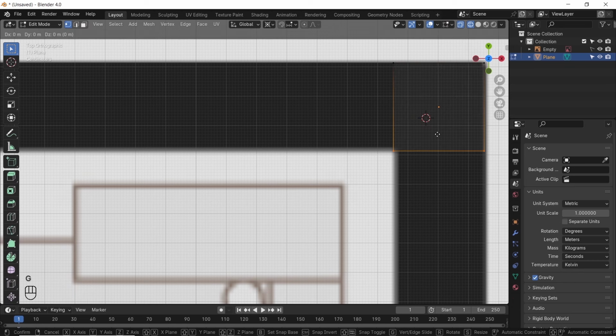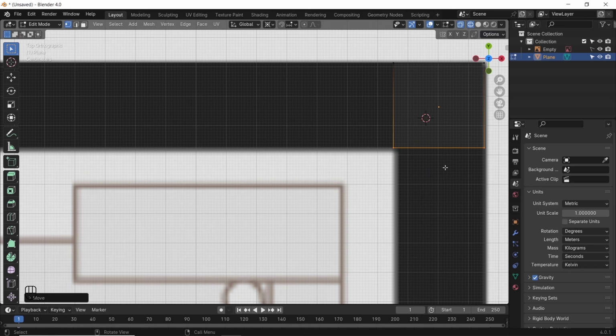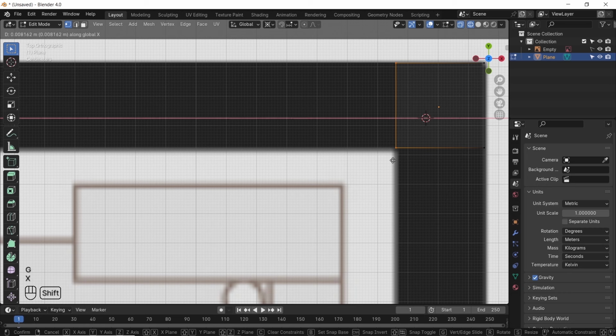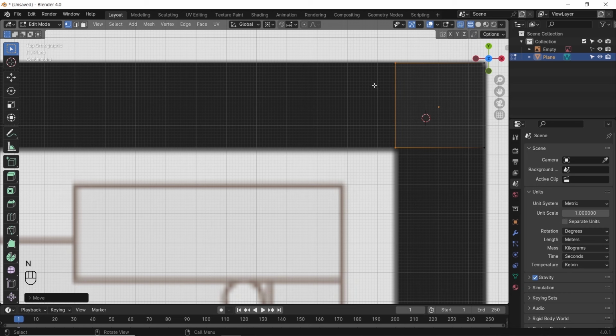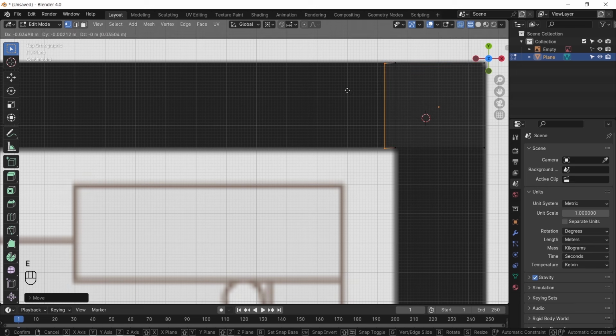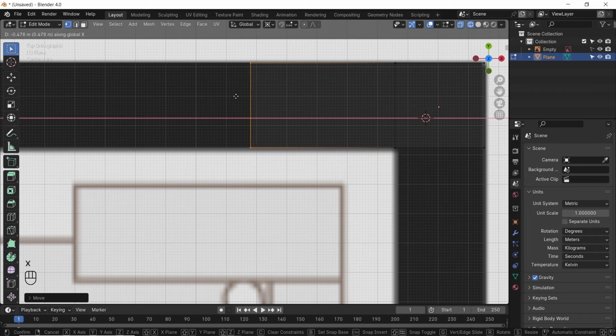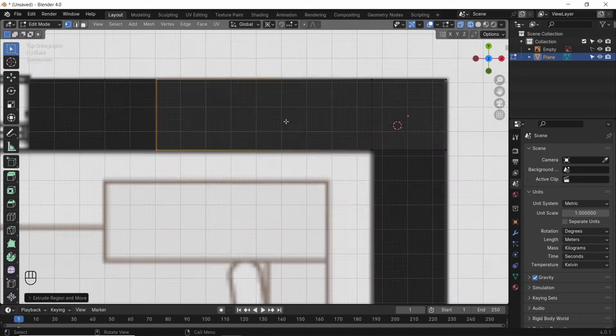The two operations we need next are simple. Extend the wall with extrude, the shortcut for it is E, and jump the windows and doors area with Shift D to copy the selected vertices. You will get it, since we will repeat that a lot. With those two vertices selected, hit E to extrude, press X or Y to choose an axis to extend along, then move it with your mouse.